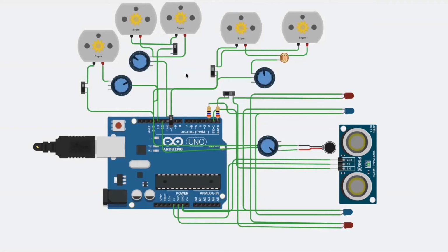And we have a smart machine which waters plants based on the sunlight's intensity. So what is so smart about this? So it has a small photoresistor, and when this photoresistor detects a lot or less sunlight, it changes its resistance accordingly. So if it's a bright day and your plants are feeling dry, the photoresistor can detect this and give more water to the plants by changing the resistance so that the motor rotates faster. But if you want only a constant supply, you can change it using the potentiometer.